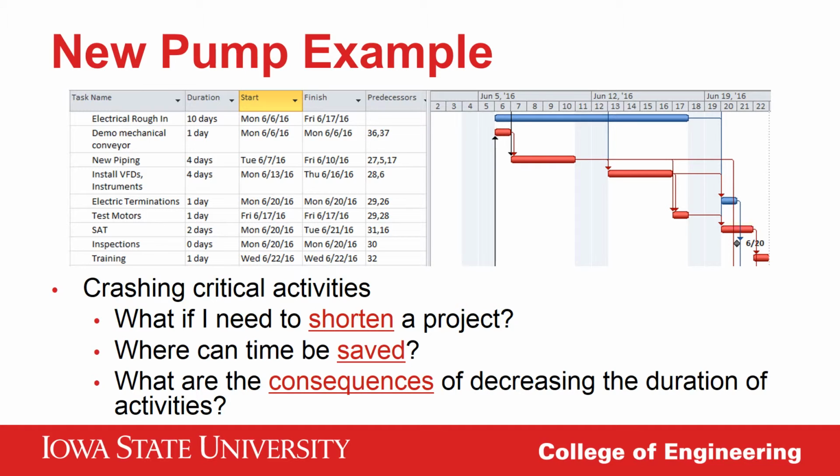So I can move demolition from June 6 to June 4, and the same for activities the following weekend. At this point, I've started production 4 days early and increased my costs around $20,000 for the weekend work. This increased cost is still less than the profit I expect to earn, so I can keep cutting. I then looked at extending working hours from the contracted 1 10-hour shift each day to 2 12-hour shifts, working around the clock, shortening the remaining downtime even further.